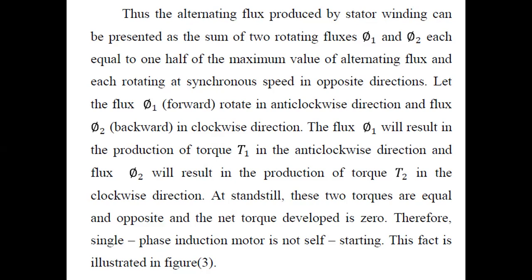The flux phi 1 will result in the production of torque T1 in the anti-clockwise direction, while the flux phi 2 will result in the production of torque T2 in the clockwise direction. At standstill, these two torques are equal and opposite, and the net torque developed is zero. Therefore, the single-phase induction motor is not self-starting. So again, we view this in the form of an illustration.